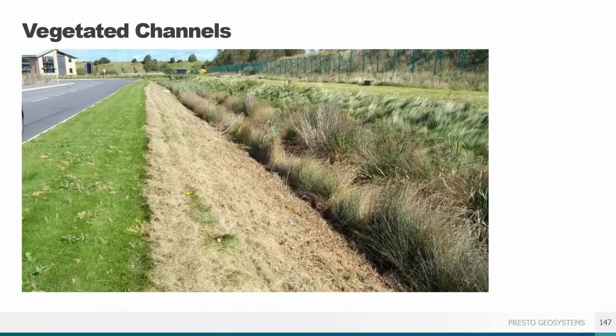Even with the liner beneath, vegetation will still grow thanks to the soil held in the cells of the GEOWEB panels. So at this stormwater overflow channel, once it becomes flooded during storm events, the side slopes are protected and the channel will keep doing its job.